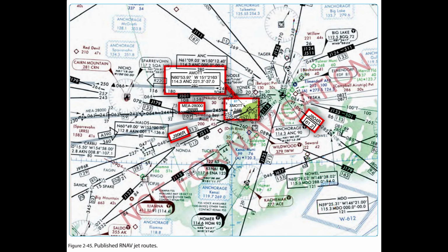6. File a minimum of 1 route description waypoint for each ARTCC through whose area the random route is flown. These waypoints must be located within 200 nm of the preceding center's boundary. 7. File an additional route description waypoint for each turn point in the route. 8. Plan additional route description waypoints as required to ensure accurate navigation via the filed route of flight.